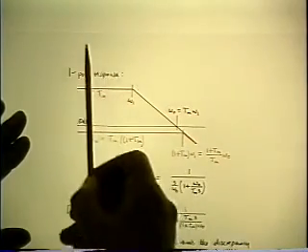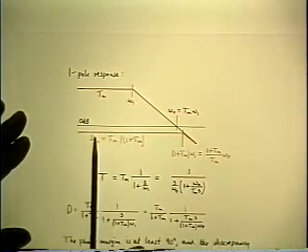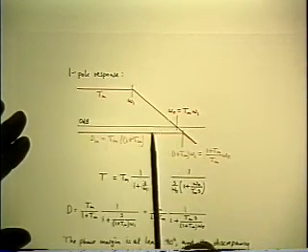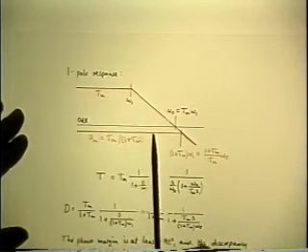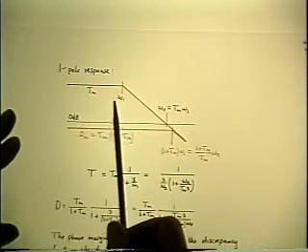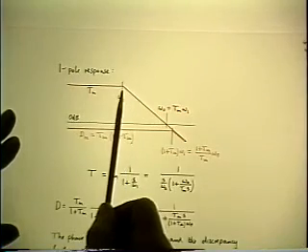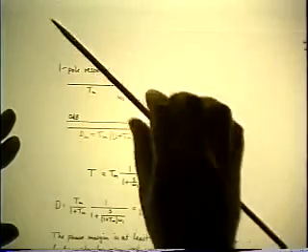And the higher the loop gain where the corners occur, the closer the wiggles would be to 0 dB, and the smaller they would get, and we don't care about them anyway. So we can simplify the problem by going in the other direction, leaving out the corner frequency that's there already. That is, pushing it off the picture.